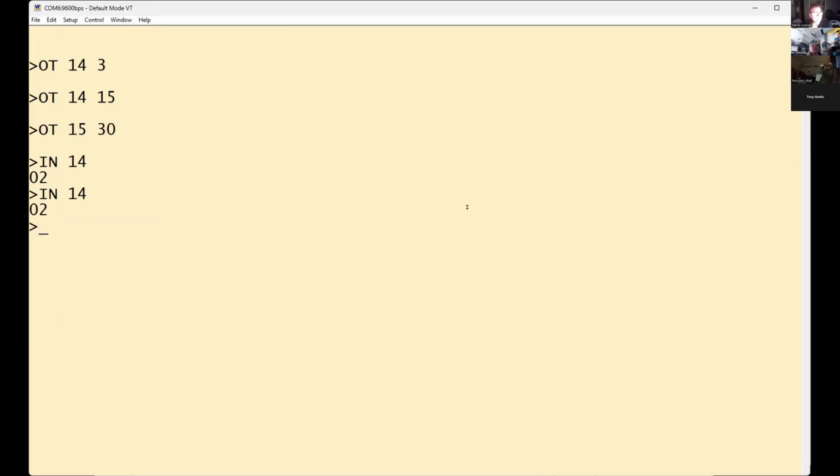So it's got to be between the bus and the console. I don't know. The 14 board works. I don't know why 14 would work and 15 wouldn't. What do you mean, 14 and 15? Well, you do an N14 and we're getting a 2, so I can do an input on port 14. So why wouldn't we be able to do the outs? But it could be the outs don't work. I don't know how to verify an out without an oscilloscope.